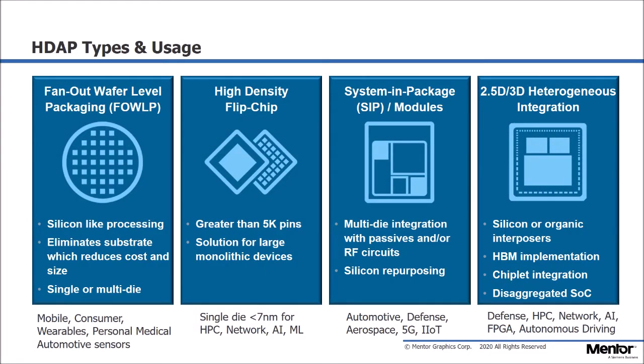Mentor created the term HDAP to categorize advanced packaging technologies that we see as disruptive to traditional tools, methodologies, and in general need a new approach to the planning, design, verification, and sign-off methodology. Of the four categories, fan-out wafer-level packaging is probably the most well-known thanks to Apple and TSMC.